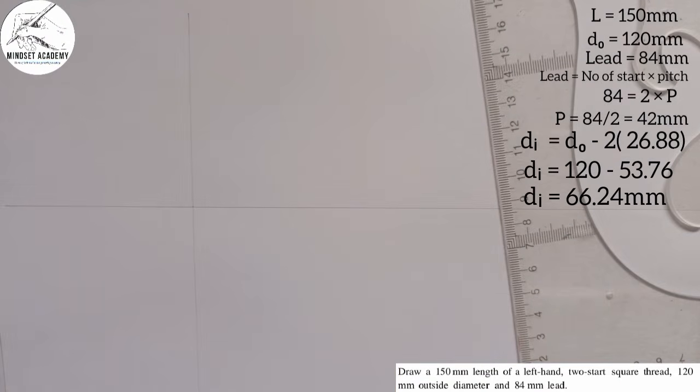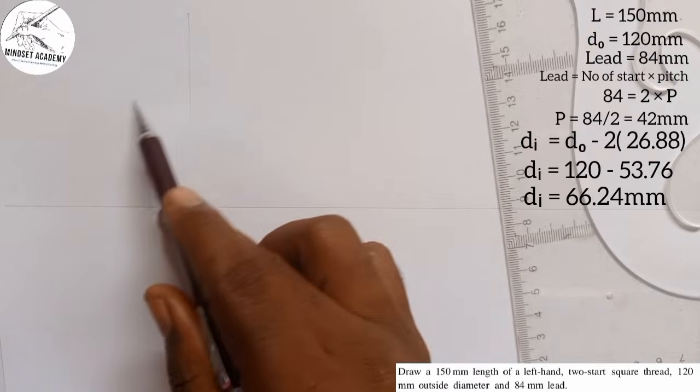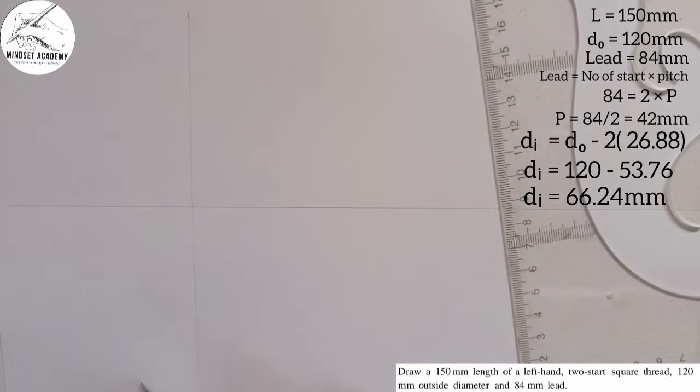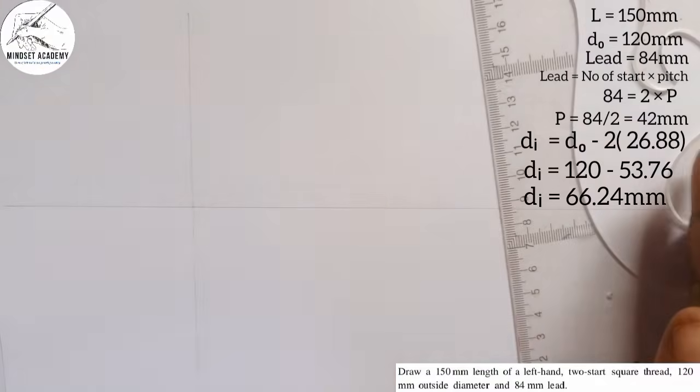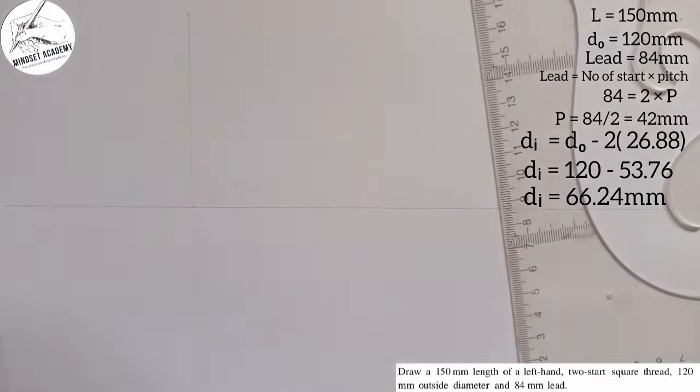And why I'm doing that is this. If I should draw my semicircle facing the right side, I am drawing a left hand screw thread. We call it left hand. That means if my semicircle is facing the right side, you say it is left hand. If it's facing the left side, you say it is right hand.